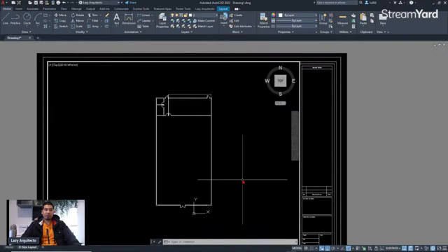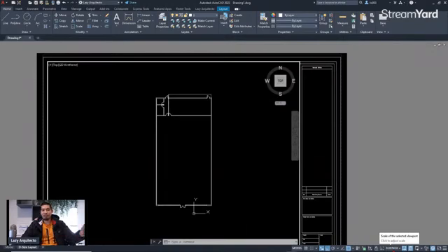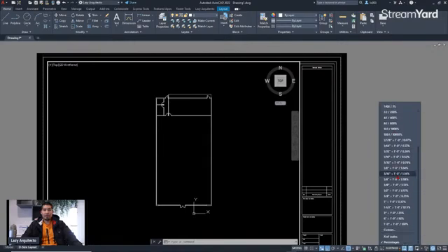And since we always want to print or PDF any floor plans or drawings to a correct scale, you need to pick a correct scale here from the status bar. Right now it's showing 0,00 and so on, which is a very random scale that you should never use. So, click that to expand it, and let's pick a scale.